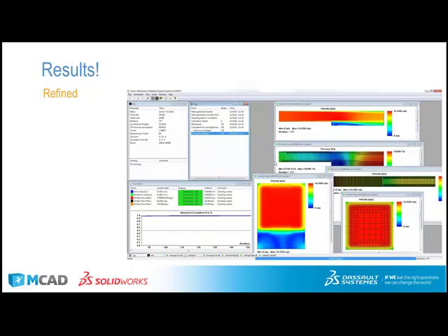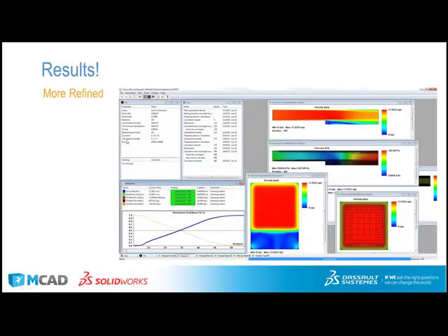So if you'll notice out here in the pressure graph, the mesh is actually deeper down here than it is up here. The boundary layer begins delaminating down here first and not up here as quickly, a result of gravity in this case. And then you can see that the boundary layer continues to build, and they have a very large mesh to accommodate that, whereas the central flow, which you can also see up in velocity, is captured by this central channel. But then when I go to the really refined one, you can see that it really tries to develop that boundary layer and show all of that effect happening inside of there.